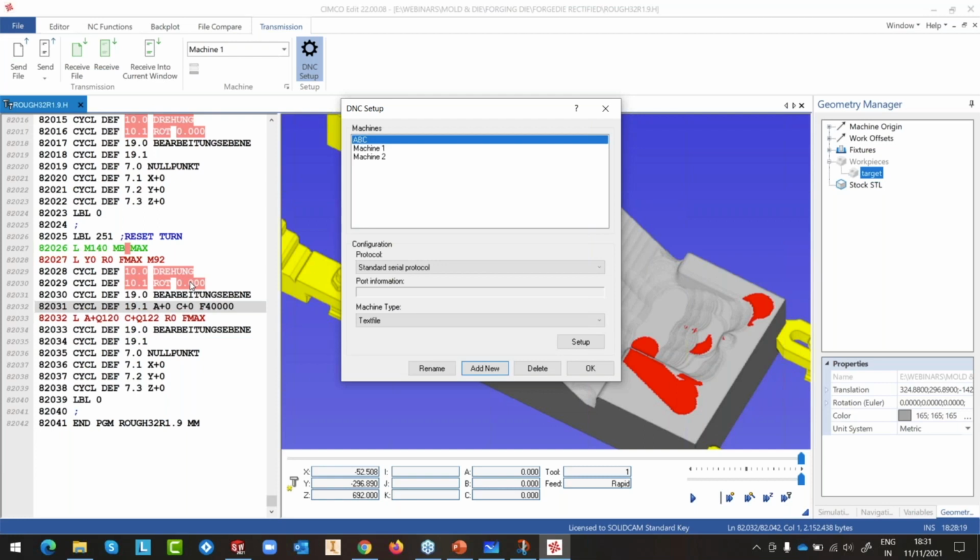I have had very bad experiences with DNC when my code had some value fluctuation, one of the digits disappeared, and there was a crash on the machine. So as far as possible, please avoid DNC, but if you cannot, and if you can ensure the cable is running very safely to the machine, go ahead.